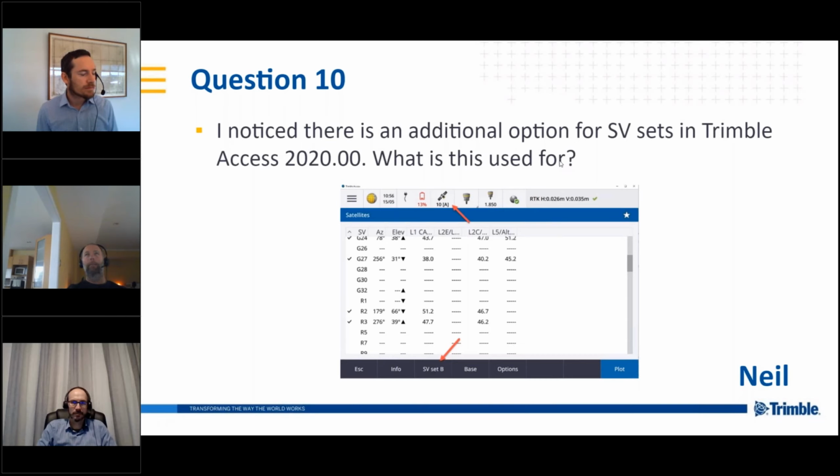So in some regions or countries or some organizations, they may have requirements to do independent measurements on a point. Historically, this may have been go and measure a point via GNSS and come back later on in the day and remeasure it for its independent check, where the satellite constellation will be in a different position with different satellites. Unlike just measuring it once, walking away, or even doing a new initialization and coming back, that wasn't good enough for some organizations. So